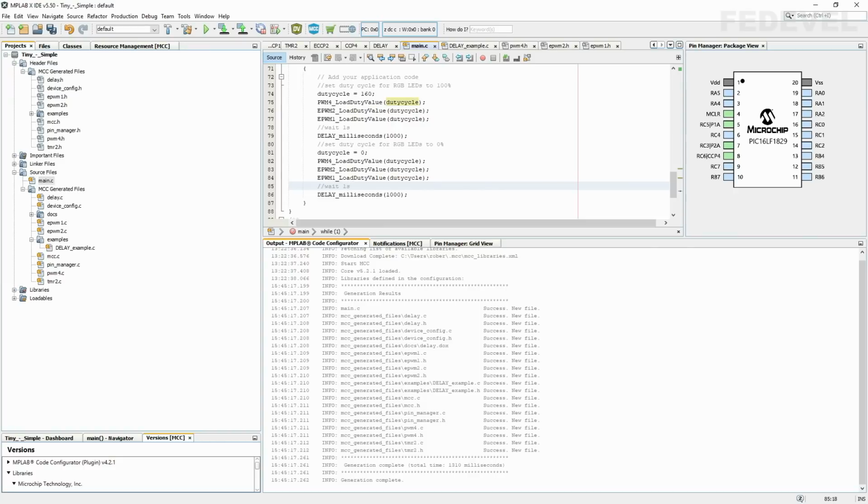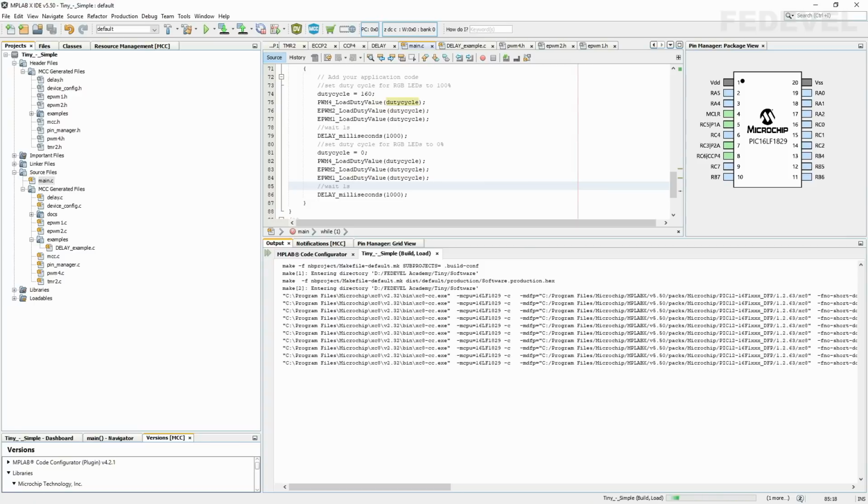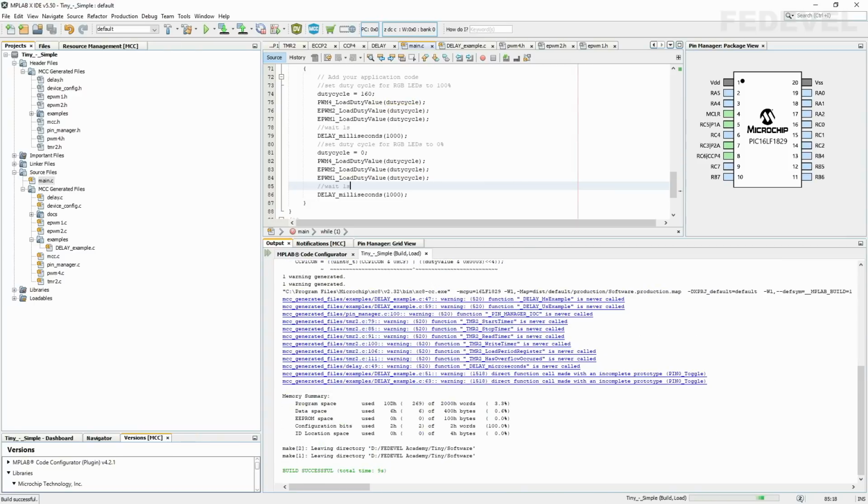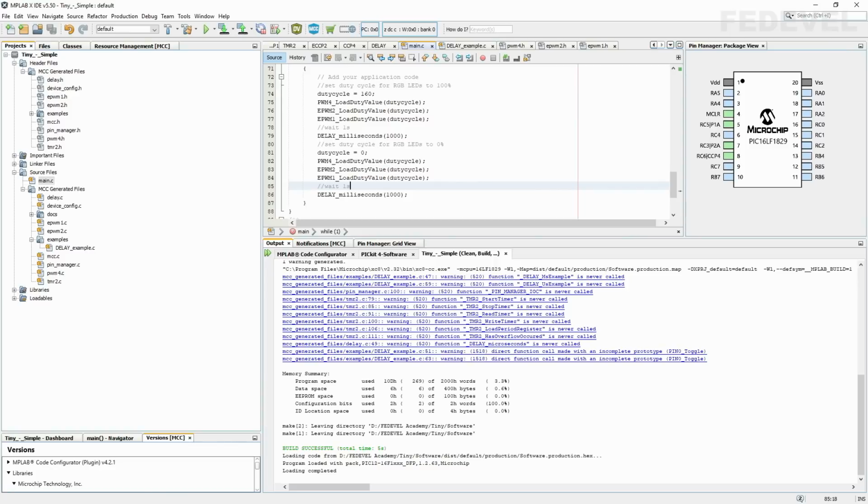Before we actually connect our board, first let's try to compile this code if there are no errors. And to compile your project, simply click here, left click. Compilation has finished and there are no errors. If there are any errors, you need to go back to your code and double check maybe what you have different comparing to our video, okay? So once there are no errors when you try to build your project, you can connect your board.